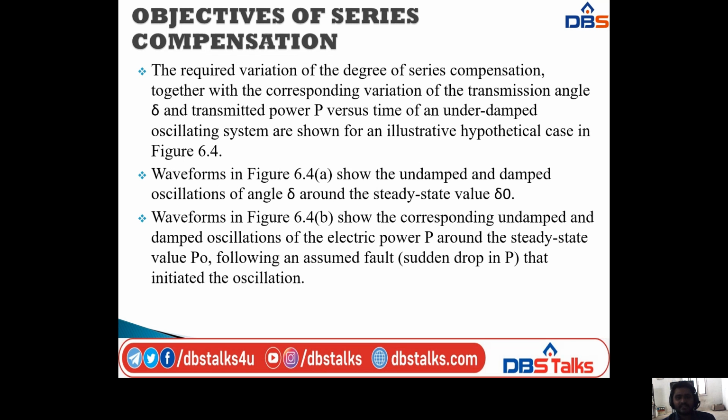The required variation of the degree of series compensation, together with the corresponding variation of the transmission angle delta and transmitted power P versus time of an underdamped oscillating system, are shown for an illustrative hypothetical case.